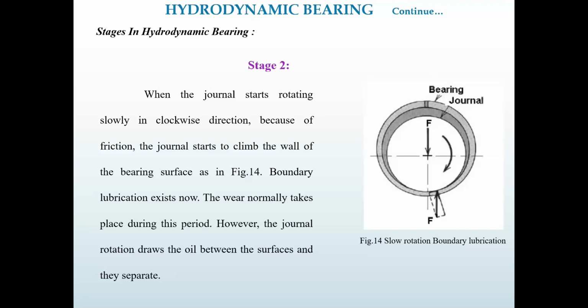Because of both these actions, the clearance in between journal and bearing increases and the shaft gets lifted. Okay, and it separates properly in between because of the oil.